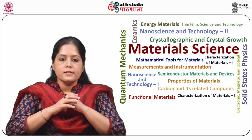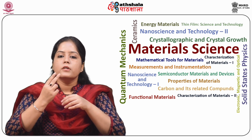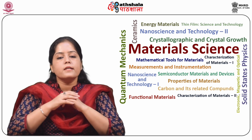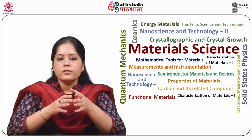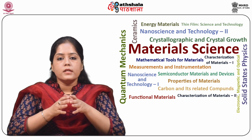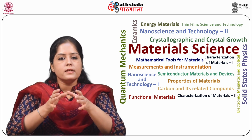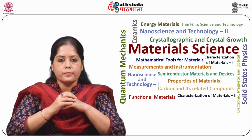The MOS capacitor can be seen as a structure consisting of two heterojunctions. First is metal-dielectric and second is dielectric-semiconductor, where the dielectric is silicon oxide. It is the high quality of the oxide-semiconductor interface that enables the practical applications of this device structure.